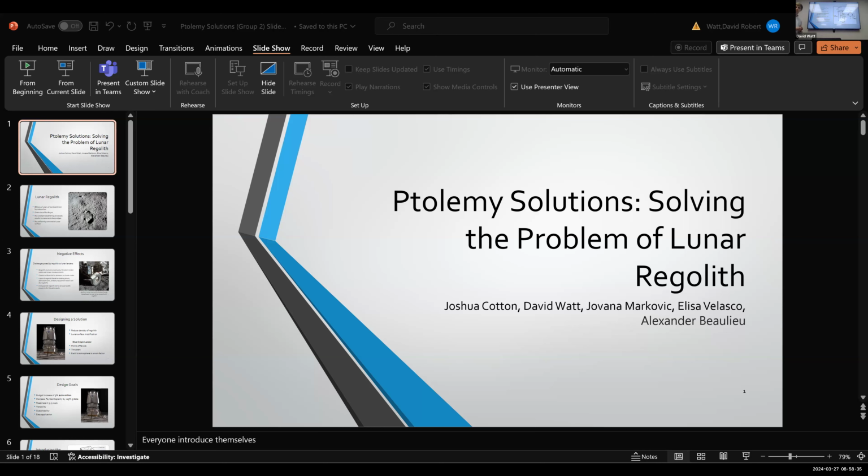Now, originally, I had the hooks made of aluminum 7075 T6, the same material as the capsule. However, that gave a factor of safety of like above 20. So for the purposes of material optimization, we decreased it to aluminum 1060-0 for a more optimized design.